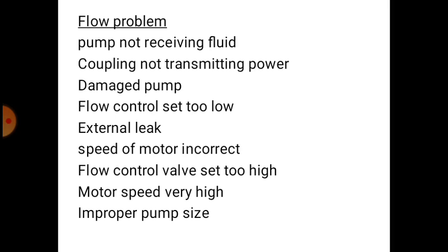Flow control valve set too high will also make flow problems. If motor speed is very high, the flow will increase, so there will be excessive flow. To reduce the excessive flow, change the motor or reduce the speed of the motor. Improper pump size: if the pump size is not correct, the flow may be low or high. So you must select the correct size pump.